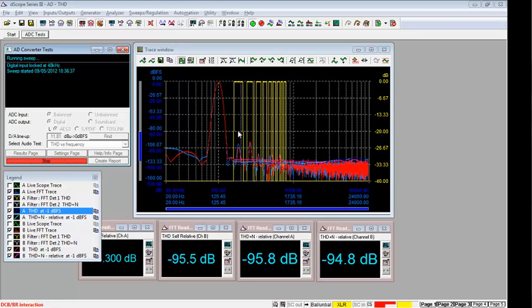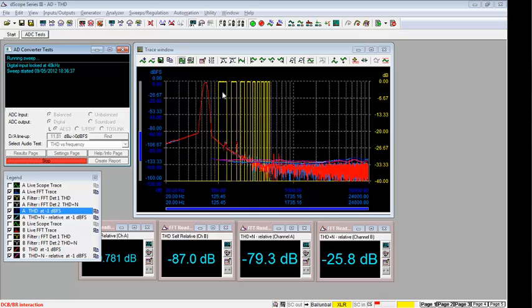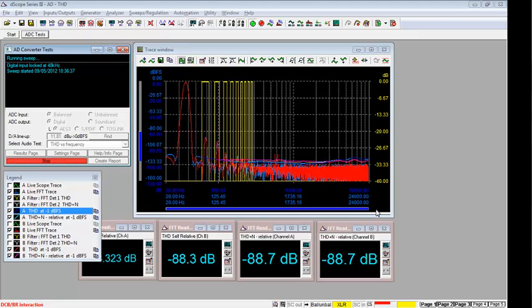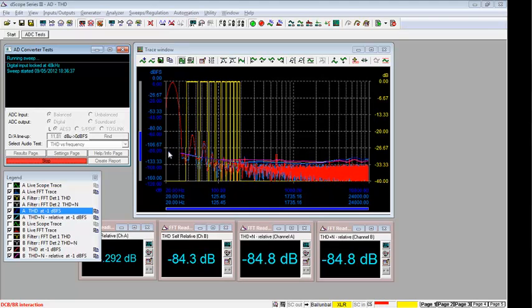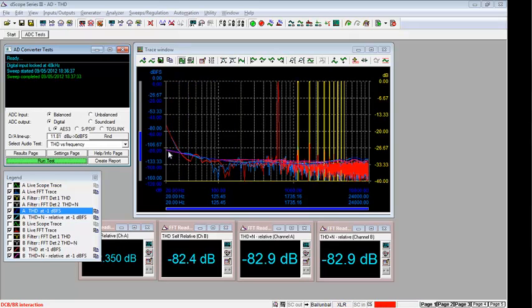Now what you'll notice is that we're getting down to low frequencies, and these filter bandwidths appear to get wider because we're looking at this on a log scale. So behind the scenes, that script that I talked about is progressively choosing larger and larger FFT sizes as we get lower and lower in frequency, and that means that we can optimize this sweep speed so it's fastest at high frequencies where we don't necessarily need this high resolution, but where we do need it, it switches into a larger FFT size for us.